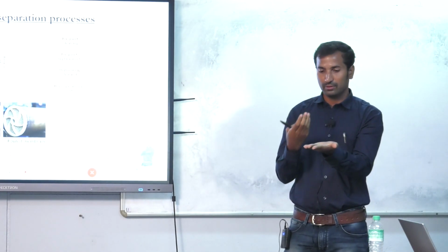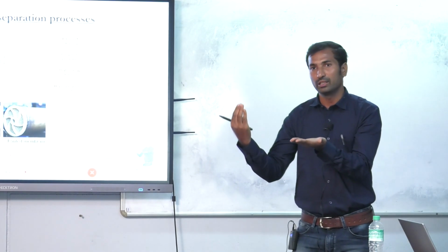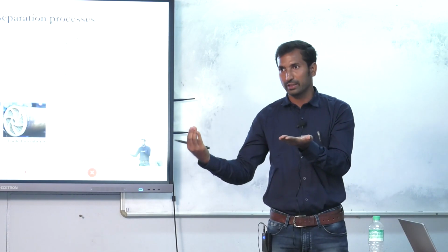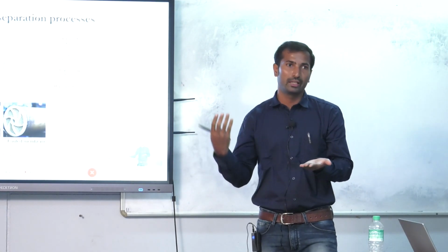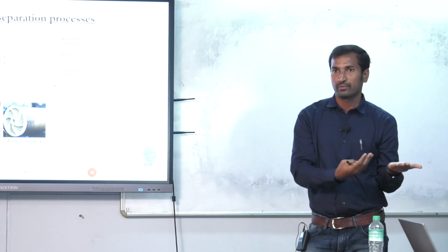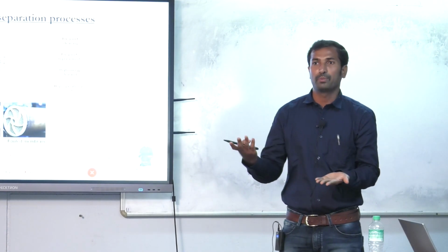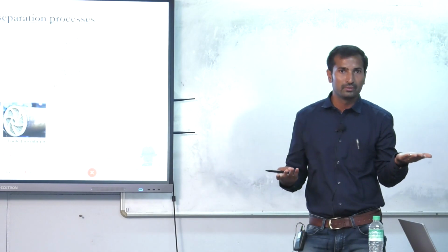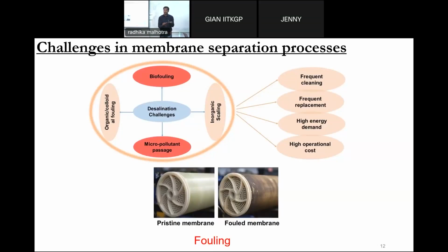You will not get 100% removal during this process. Then what typical industry people do is chemical cleaning. Mostly they use dilute acids or dilute bases like sodium hydroxide or hypochlorite. These are the chemicals they use: the dilute acids and hypochlorite.